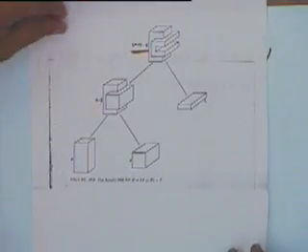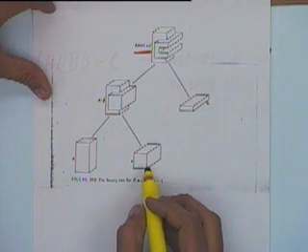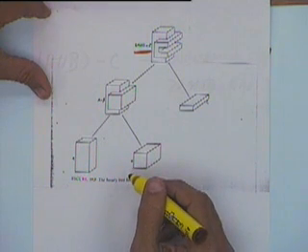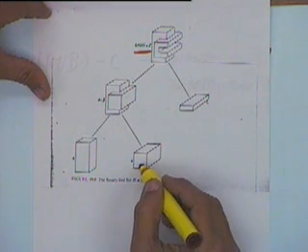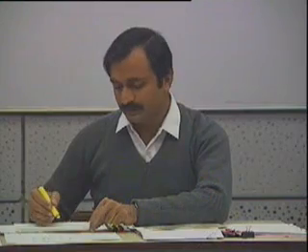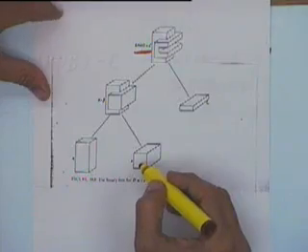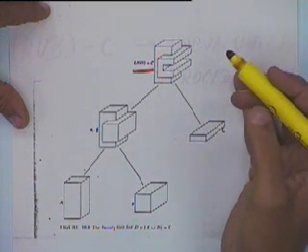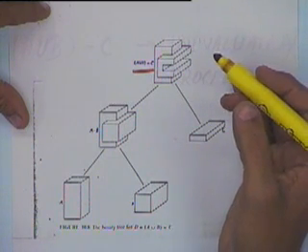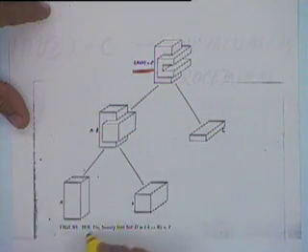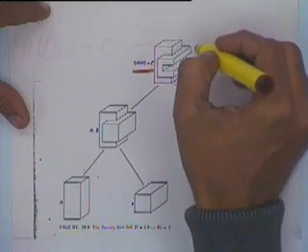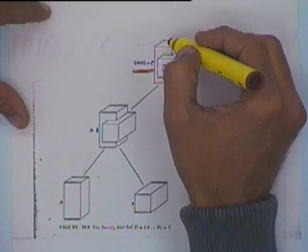The primitives, like in this case, will be represented using some other modeling technique, let us say BREP. There can be other modeling techniques that we use for that, but right now we will talk of only the BREP. If you are using some other technique here, when we evaluate this model, this solid will also be represented in that technique, not as a BREP normally. So whatever method we are using for representing these primitives, after evaluation we will try to get this model also in the same representation.